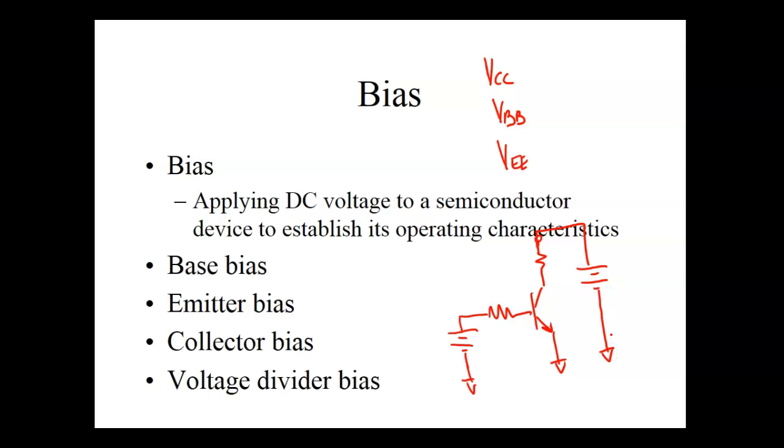Of course, this is not very good because now we have to have two power supplies. So when you do this lab, and Lee's already done it, you couldn't use the trainer's batteries because the trainer's DC power sources are connected like this, so I can't set this circuit up. What did you have to do, Lee? You had to get another power supply. We can use one power supply off the trainer, but we can't use both of them because they're not connected correctly.